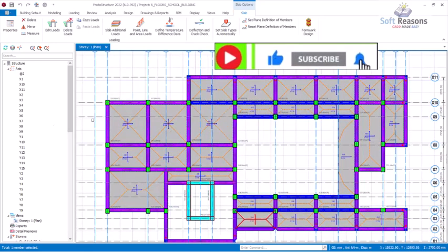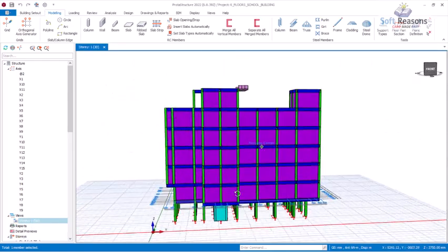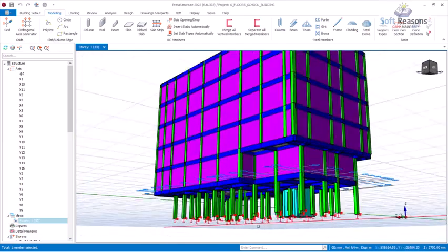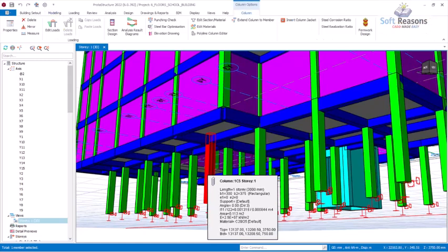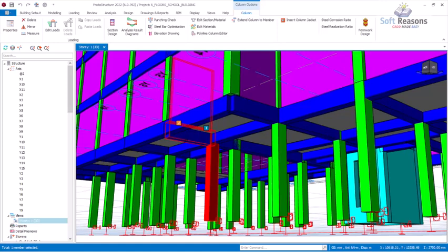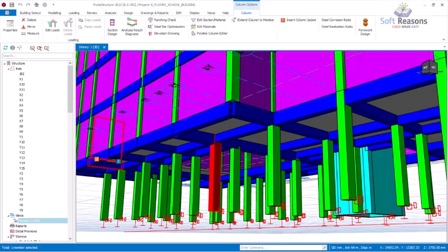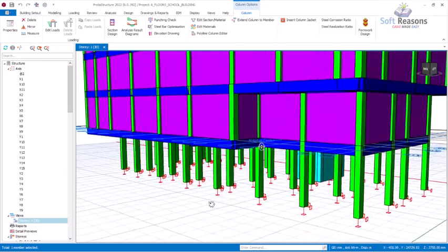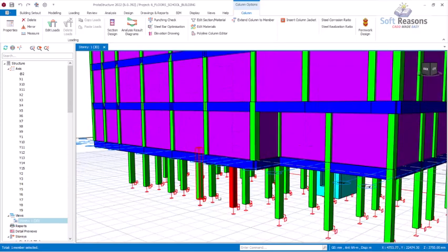Okay, this column carries the whole floors. So as you navigate back to the 3D, you will see what I am trying to explain to you right away. Now if you come over to this side, you can see the story 1 through foundation columns, and then this column carries these beams that carry the slab, which is a cantilever being carried at the first floor all the way to the last floor right there. So you can see the load that is coming up to this particular column.